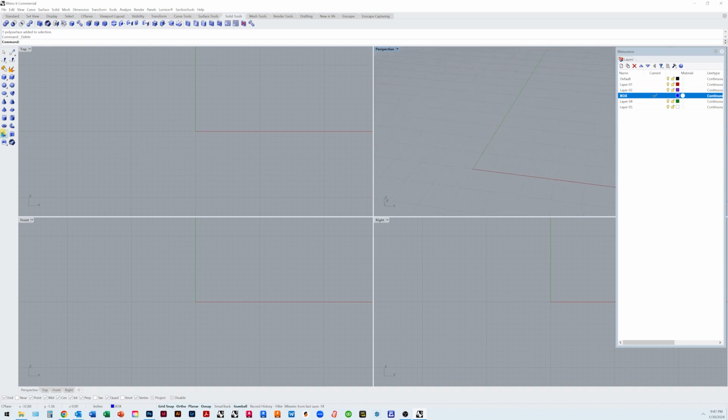Let's look at the other tools that we have. We've got some basic shapes here. Let's just go down. We've got the sphere. If I click the sphere here in the center origin, let's see what happens. Let's go out. Boop, I've got a sphere. Let's see what happens when we want to put in dimensions. We'll take the sphere, hit the center there, and then it'll ask you here, you can enter the radius.